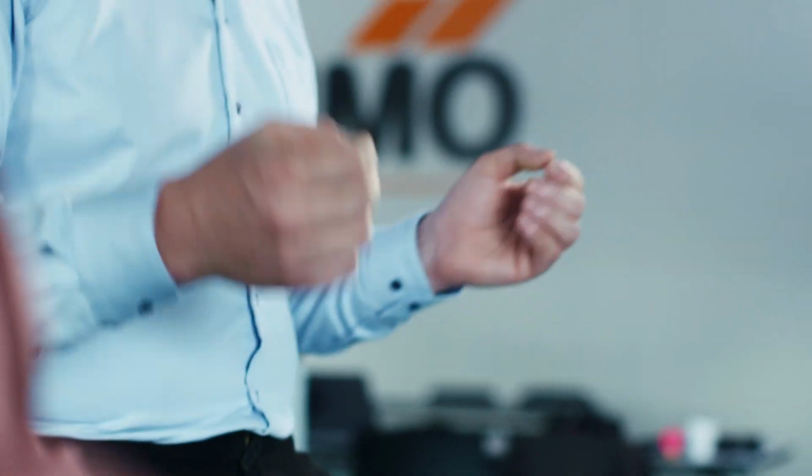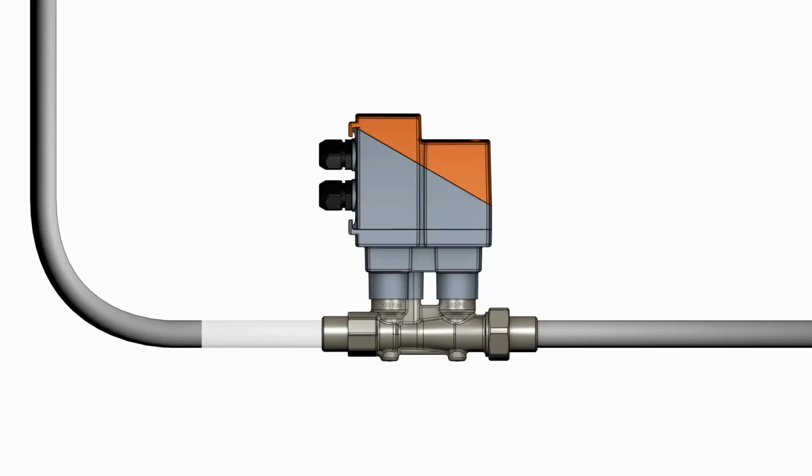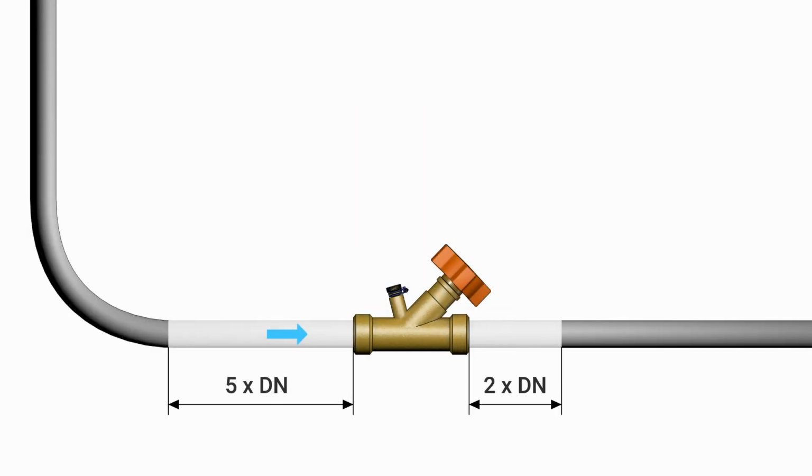If your system is likely to experience regular and significant pressure changes, electronic valves need to adapt their position to suit those new pressures. It's very rare that we experience large and significant pressure changes regularly in HVAC systems, however it's worth remembering. It's no secret that any device that actually measures flow needs a number of straight diameters upstream and sometimes a number of straight diameters downstream. So if you actually want to measure flow using any technology, you will need to allow the required number of straight diameters for that particular device.